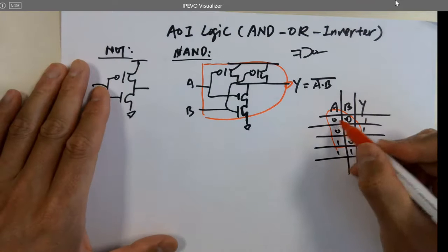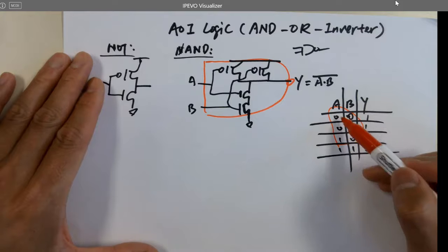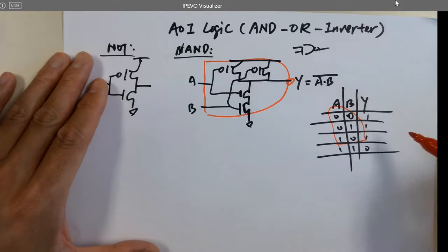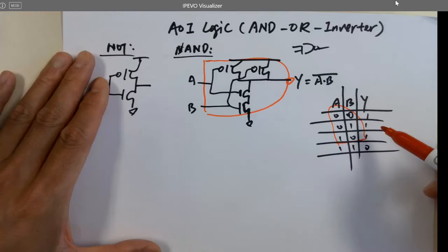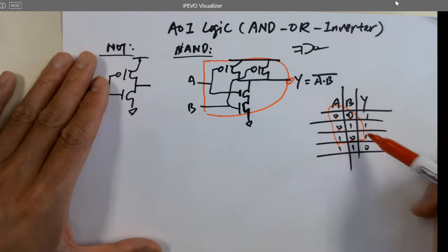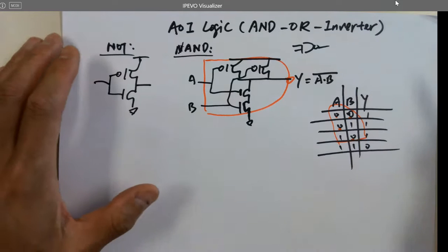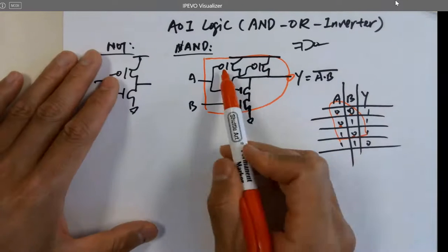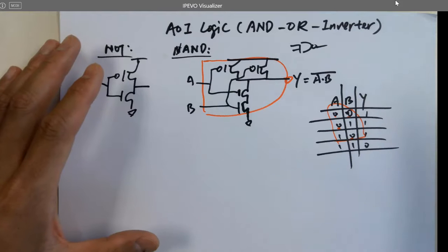So if you look at these inputs, what's the pattern here? Could you summarize it in English instead of logic? You have 2 zeros, you got one 0, or this 0, or it can be both zeros, right? So you can summarize it in English as: whenever one of these 2 PMOSes has a 0 for the gate, it should be pulled up to VDD.